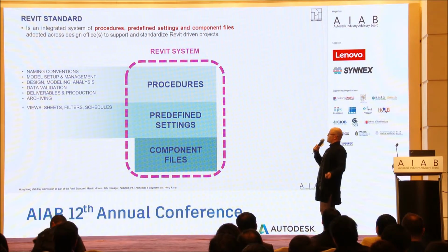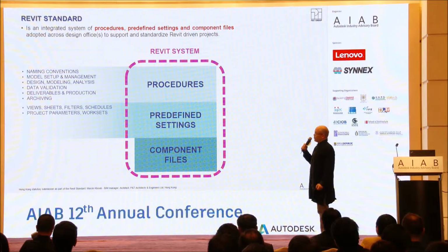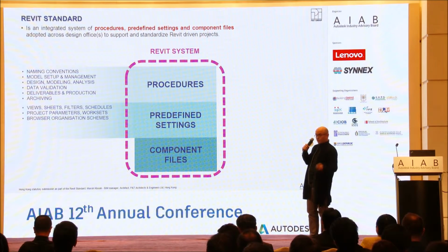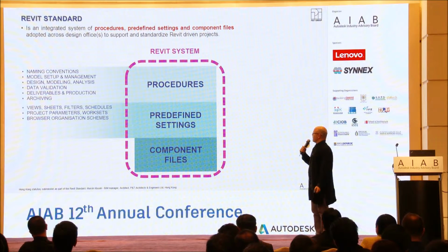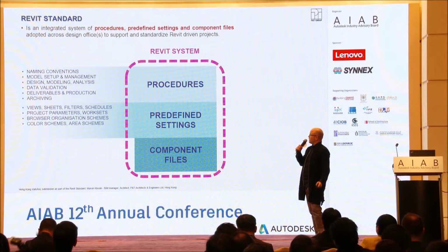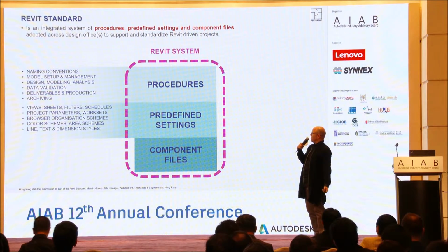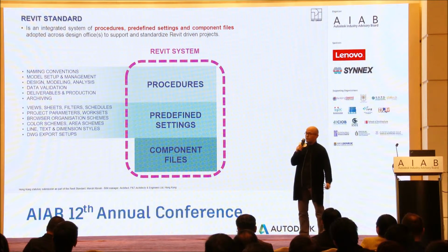So views, sheets, filters, schedules, predefined. Project parameters, worksets, workset structure and naming. Browser organization schemes, color schemes, area schemes, line, text, and dimension styles, DWG export setups.